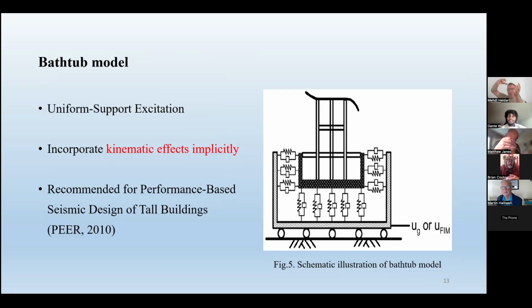It's not the inertial mainly, right? So you have soil moving around during the free field movement of the soil during the earthquake, and this movement applies loads pretty much like when you have a slope or even when you have, for instance, excavation. The movement of the soil causes that load, not that we apply a load to the structure, right?